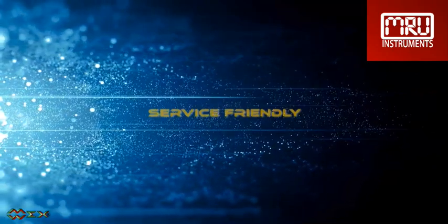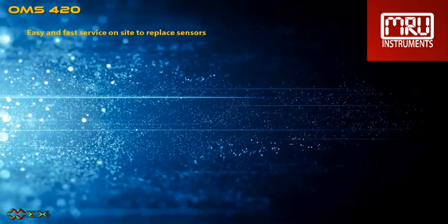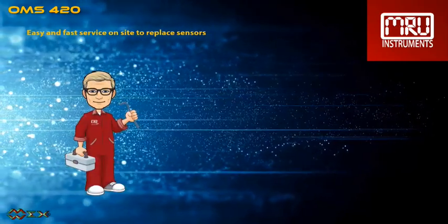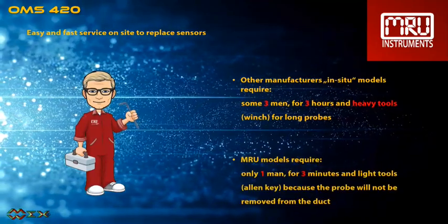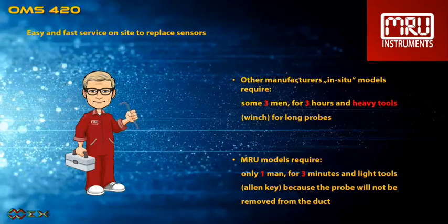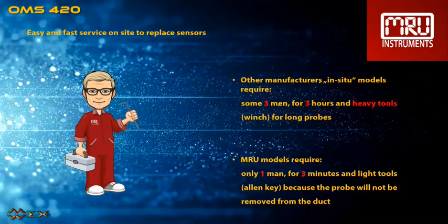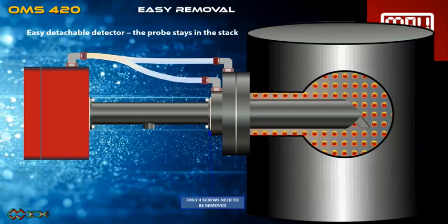The OMS is super service friendly. Other manufacturers' in-situ models require some 3 men for 3 hours and heavy tools to remove the probe from the stack. MRU models require only one man for 3 minutes and light tools. We only remove the transmitter, the probe stays in the stack. Let's see how this is done. Only 4 screws need to be removed.